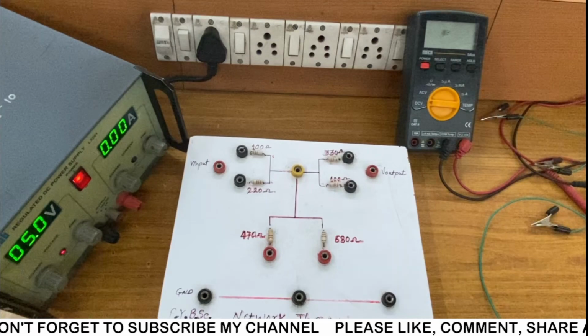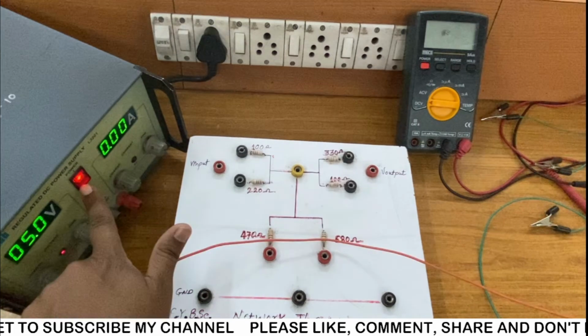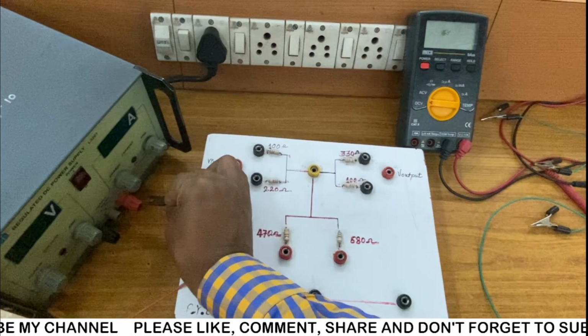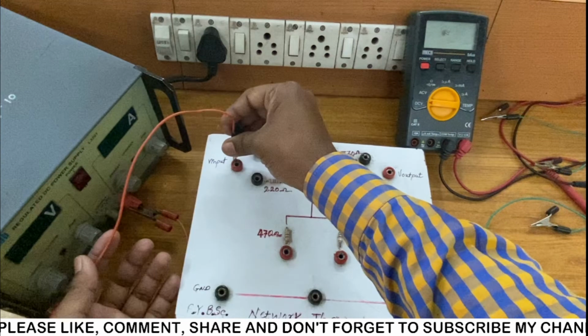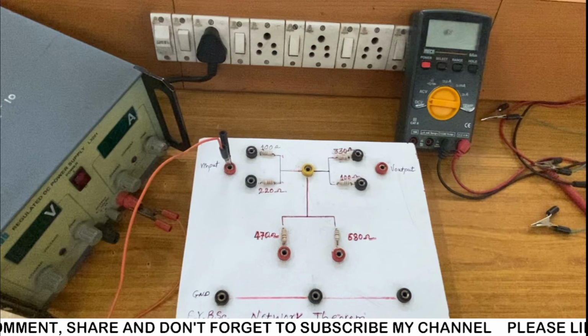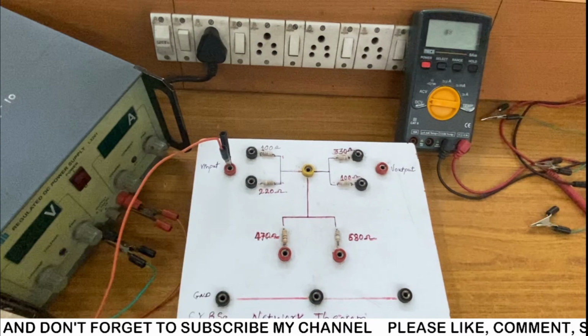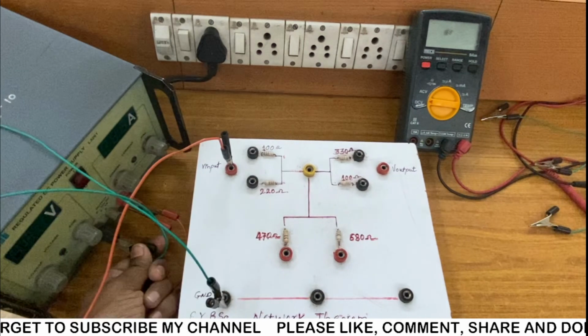So we are keeping V1 constant at 5 volt. I am going to shut down the supply and make the connection. I am going to connect the plus voltage to the input of this particular socket. The ground terminal should be connected to the ground. We have combinations of 100 and 220 at R1, 330 and 100 at R2, and 470 and 680 at R3. So we can have very many possible combinations.